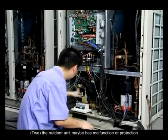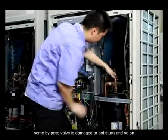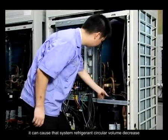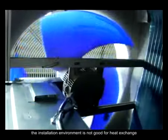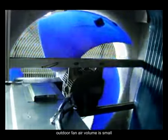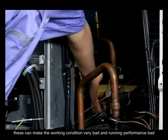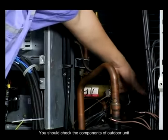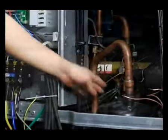2. The outdoor unit may have a malfunction or protection. Some bypass valve is damaged or stuck and so on. It can cause the system refrigerant circulation volume to decrease. The outdoor unit air return is short circuited, or the installation environment is not good for heat exchange. The outdoor fan air volume is small. These can make the working condition very bad and the running performance bad. You should check the components of the outdoor unit and judge if their action is normal when the system is running.